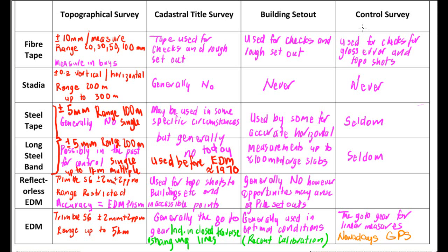We'd drilled a hole in the ground, and the top of the pile was being positioned 6 meters out of the ground, so what I did there was put a bolt with some tape around it that the reflectorless could measure to, and I could be off to one side, and the contractor could move the piles around.